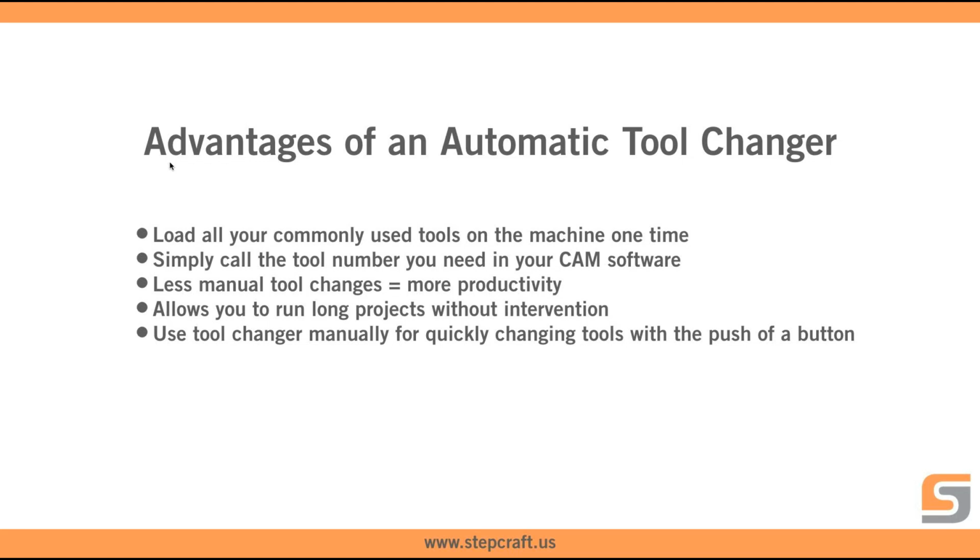One of the nice things when you're programming a job is once your tools are on the machine, all you need to do when you're doing the CAM, and I'll show you that in a minute, is simply call the tool number that you need. So you don't need to really remember anything. What we usually do is we keep a notepad, or we keep a standard where certain tools are in certain locations. So when anybody is doing a job and they're programming something, they know, okay, tool 1 is always this bit, tool 3 is always this bit. However you want to do it in your shop, that is one thing that makes things really nice: simply change the tool number and you're good to go.